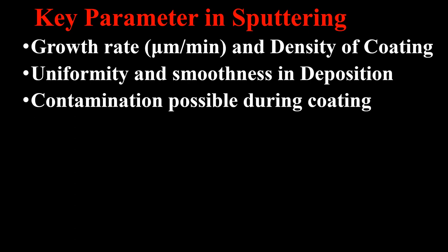film. And also there could be contamination in the environment of the sputtering chamber. So it is highly desirable, in terms of getting a good quality film, that the vacuum chamber or the sputtering chamber is fully evacuated with no contamination, and also the incident inert ions should not interact with the material on which the source material is placed.